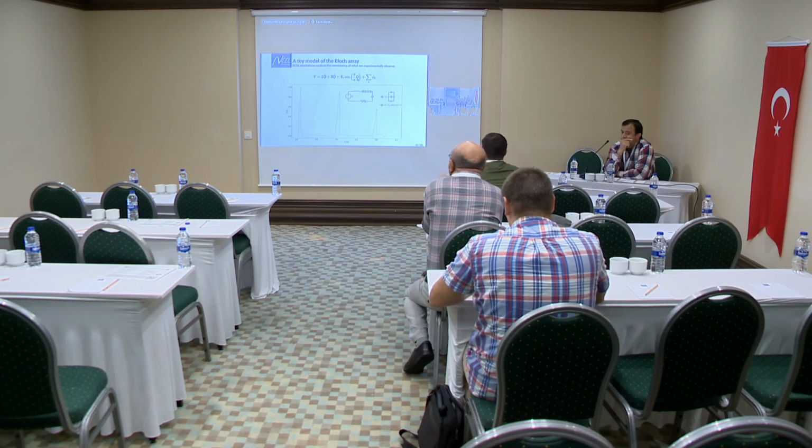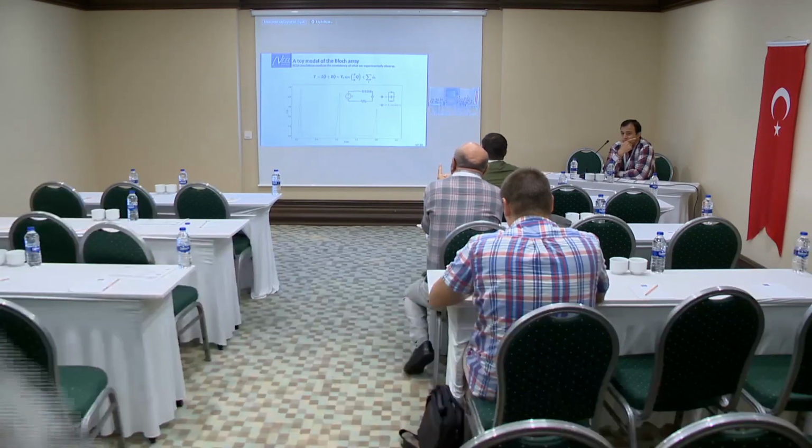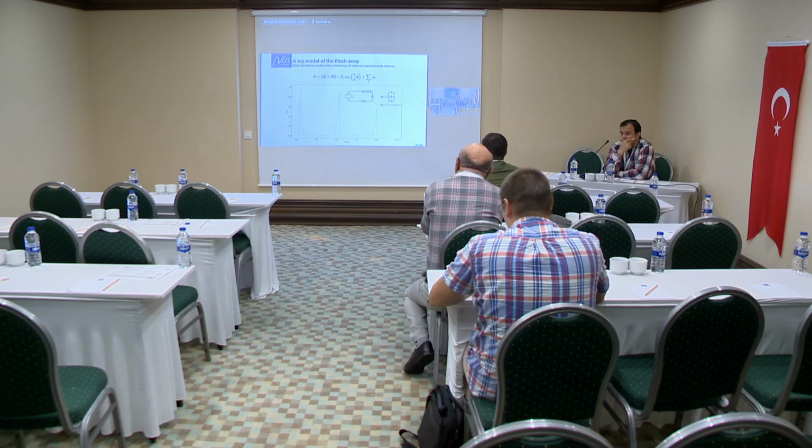Really it's different. But maybe for your purpose, this is enough. But sometimes it seems dangerous. And the first term also, inductance is Q-dependent, because there are calculations of Alexander Zorin related to this moment, because of Bloch inductance, so also a periodical function of quasi-charge.